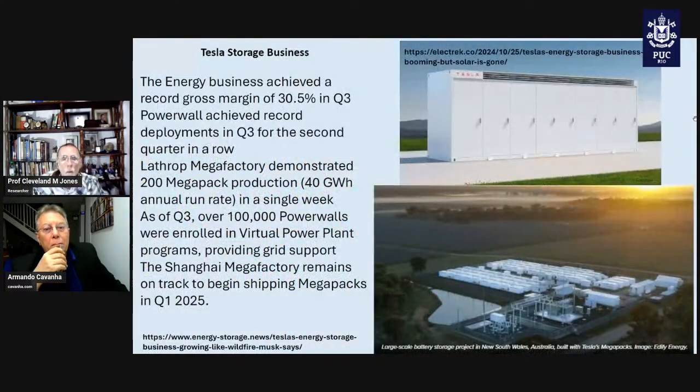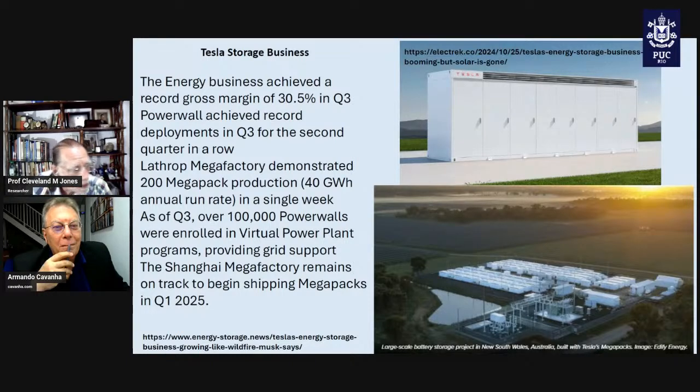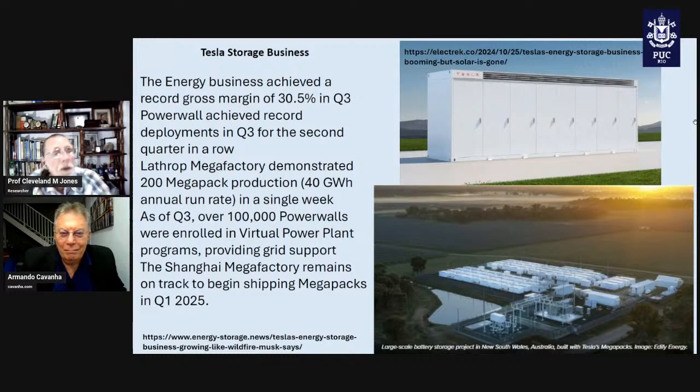But I tell you, one of the things that we read a lot about is, for example, Tesla implementing these large scale energy storage systems in Australia, Saudi Arabia, wherever, with basically kilometers of battery. It's very expensive. And this is just scaling up basically Powerwalls. You have hundreds of them. And this is a very inefficient way of providing large scale storage, because these are not efficient storage units when you are talking about gigawatts.